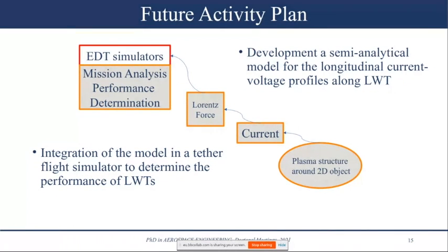So finally, when we have a model for a plasma structure, we can develop a semi-analytical model of the current voltage profile along the tether to compute the average current and Lorentz force, which takes part in a flight simulator to determine the performance of the low work function tether.